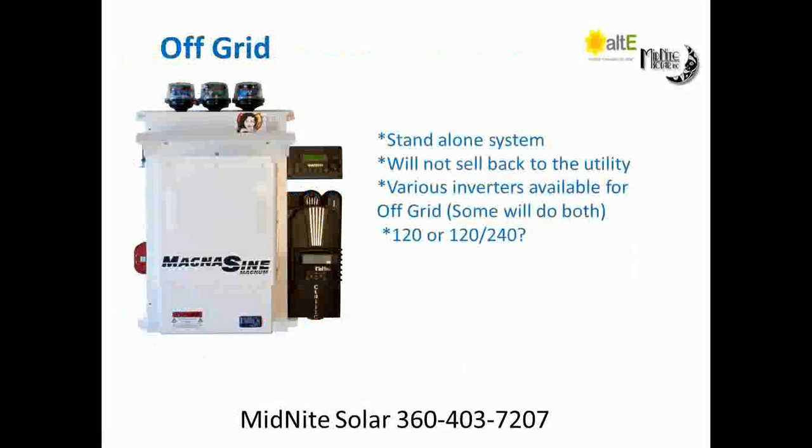Various inverters to do this with. There's Magnum, Xantrex, SMA, Outback. All the major players do off-grid and do it very well. The determining factor in determining which inverter you want, basically what you need to start out with is, do I need 120 or do I need 120-240? How big of an inverter do I need? And in the off-grid world, that's solely based on the biggest load you plan on running, or actually the opposite can be true sometimes. It can also be based on how big of a battery charger do you need.